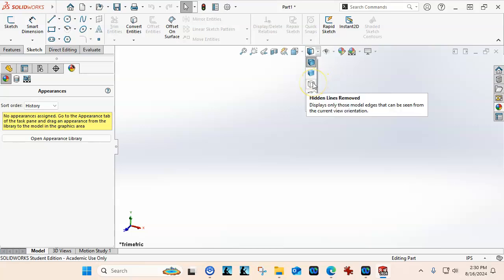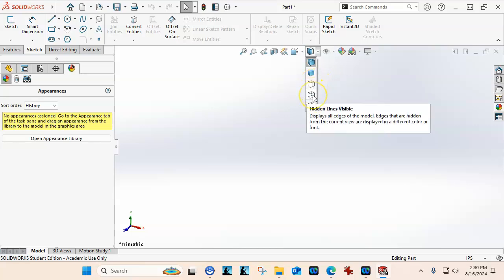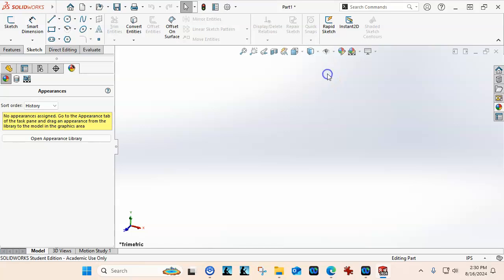And then the wireframe or hidden lines removed, hidden lines visible, and the actual wireframe where everything's solid and good luck figuring out what you're looking at. But the actual wireframe is handy for some of the CAM programs where toolpaths might not be visible with the solids on an interior piece of geometry, that it would allow you to be able to see those.